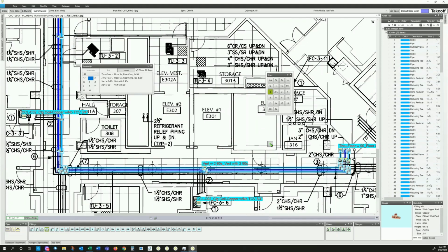We have a very impressive library of assemblies, whether it be for equipment hookups, fixture hookups in wall, underground hookups for water closets like we looked at, or like I said, boilers, chillers, cooling coils, but also more takeoff functional assemblies like these here that can really speed up the time it takes you to do simple takeoffs where you'd have to add vertical pipe and 2 90s independently, but it's going to capture that all at the same time. But in a seamless way that pulls from whatever size you have selected and allows you to just continue with the takeoff from there.